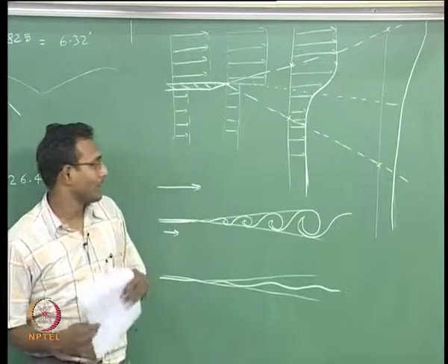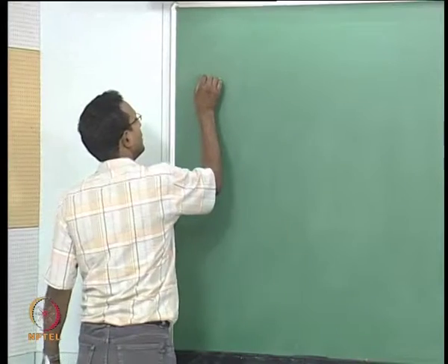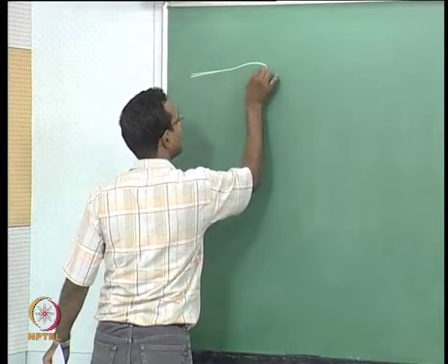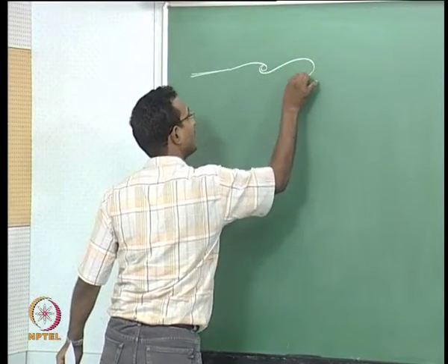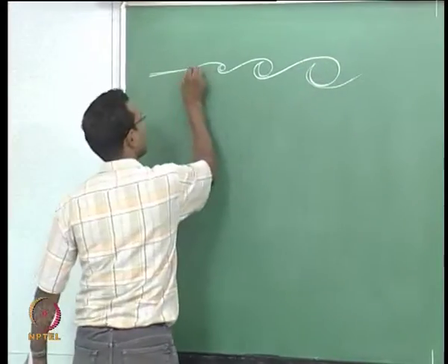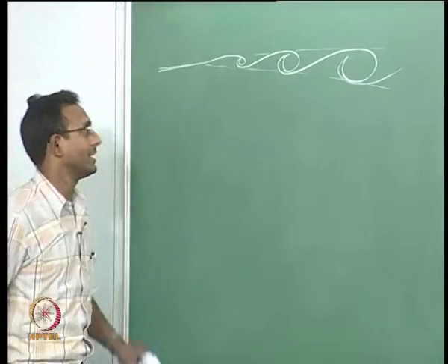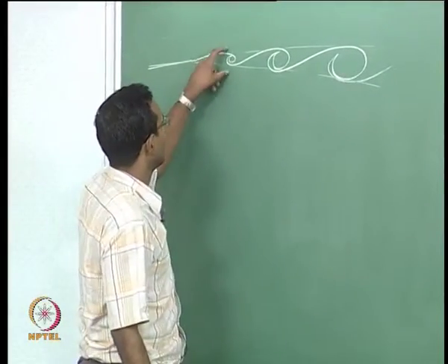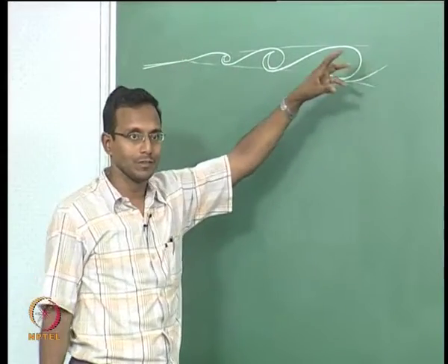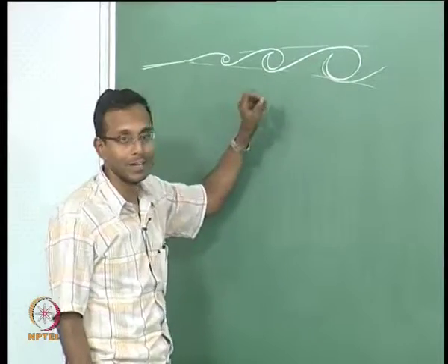Now people wanted to understand this in compressible shear layers. Something like this, and I am going to say that is my shear layer, having some large scale structures that are growing as they go out, and the vorticity strength will keep on decreasing for all of this because it is spreading out more.